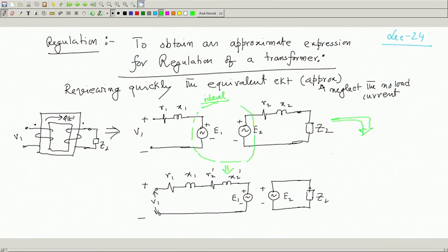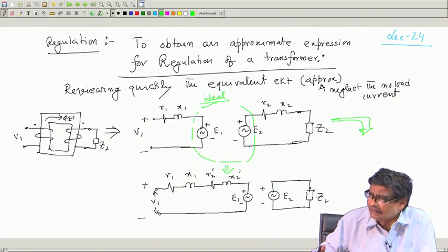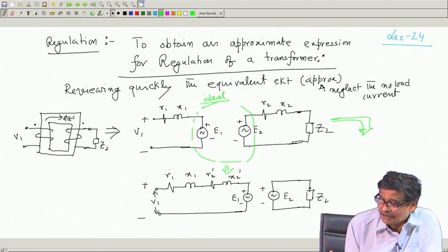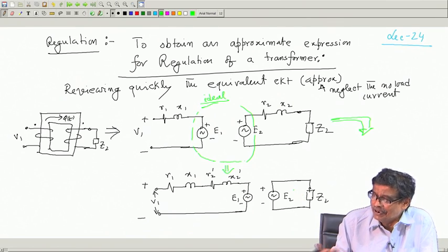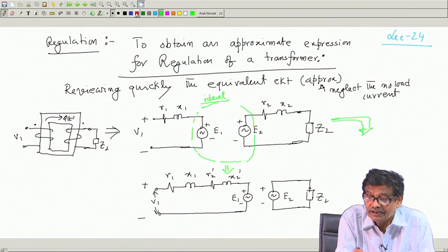You show V1 here. It means that you are assuming the secondary coils have no leakage flux and resistance. All resistance and leakage fluxes are there on the primary side. There are many ways of looking at things. This one could also be drawn like this.